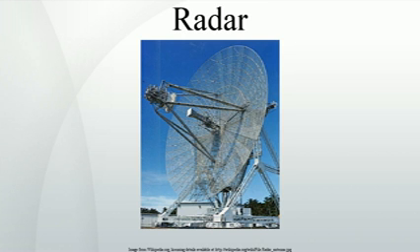Weather radar uses a low PRF. Coherency requirements are not as strict as those for military systems because individual signals ordinarily do not need to be separated. Less sophisticated filtering is required, and range ambiguity processing is not normally needed with weather radar in comparison with military radar intended to track air vehicles. The alternate purpose is look-down shoot-down capability required to improve military air combat survivability. Pulse Doppler is also used for ground-based surveillance radar required to defend personnel and vehicles.